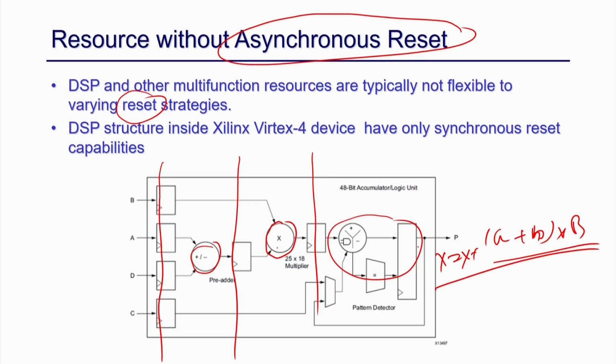You can do the whole thing in the same multiplier, and not only that, in this design you can have 3 sets of registers as well, so that the delay becomes less. So, you can understand what the different variations of operations are that can be performed by a single DSP, and it is your choice. You have all these configurations, you can choose either only multiplier, multiply and add, pre-adders, one set of registers, 2 sets of registers, 3 sets of registers. All these things can be done, and it is a very efficient and very fast dedicated unit.